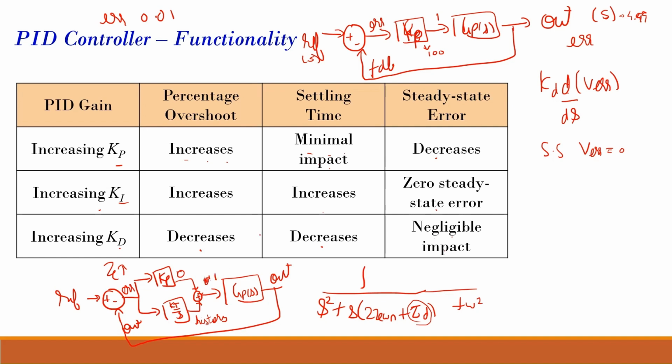It will get that value of 1 that was required to get the output of 5, because my integrator has a history term. So even though the error is 0 over here, my integrator can give the value 1, because the history of the previous errors has been summed up until I finally get a certain value which will make my plant reach the steady state value. So that is the advantage of an integral controller. That is how it drives the error to 0, because it is summing up the error.